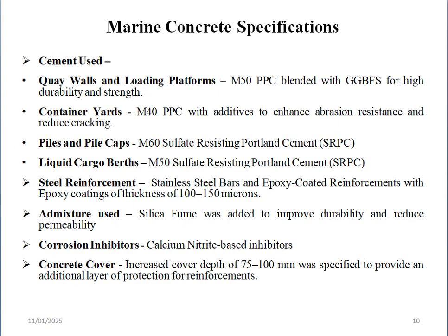Here are the marine concrete specifications. Cement used: for quay walls and loading platforms, M50 PPC blended with ground granulated blast furnace slag for high durability and strength. Container yards: M40 PPC with additives to enhance abrasion resistance and reduce cracking.